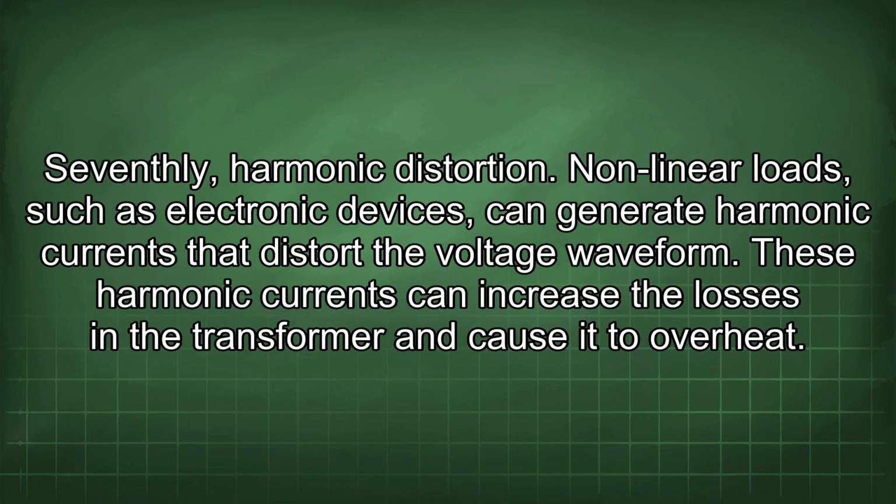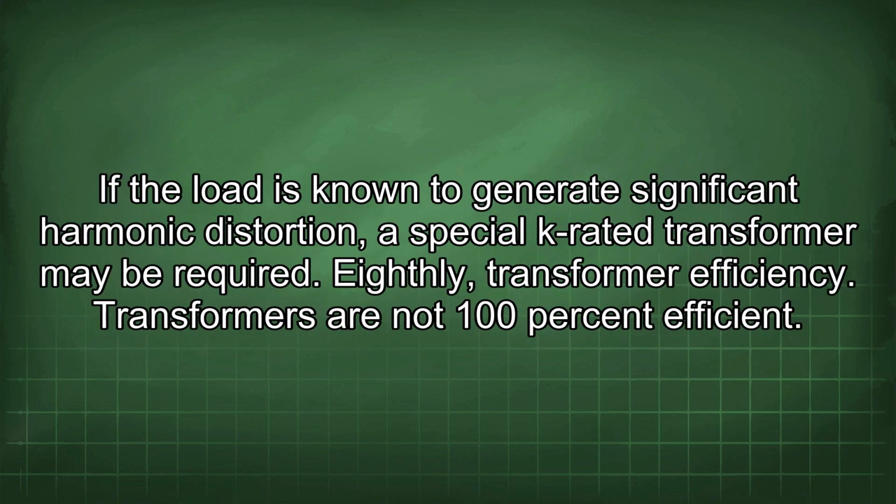Seventhly, harmonic distortion. Non-linear loads, such as electronic devices, can generate harmonic currents that distort the voltage waveform. These harmonic currents can increase the losses in the transformer and cause it to overheat. If the load is known to generate significant harmonic distortion, a special K-rated transformer may be required.